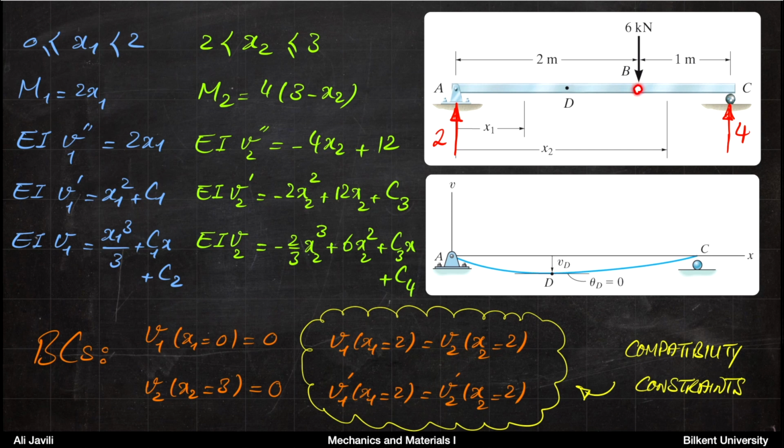The shear force itself has a jump at point 2. So in the previous slide, since we also talked about the shear force, we didn't start with having equality. But in this slide, it would be perfectly fine to have the equality because we are talking about quantities that are actually continuous at 2. M is the same, so the second derivative, first derivative, and basically the deflection are the same.